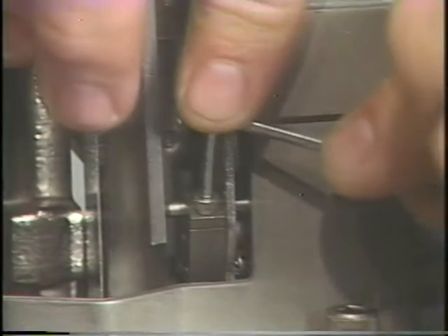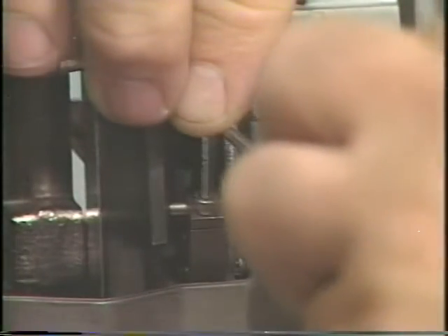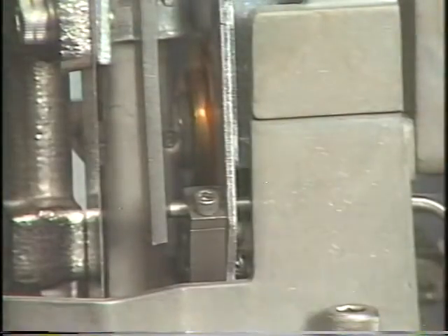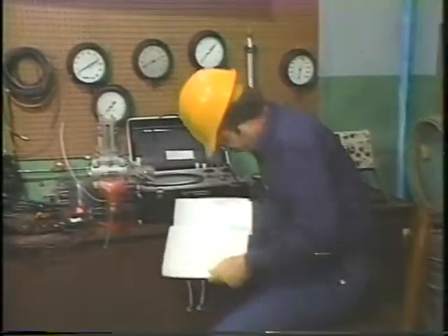Now, when Bob gets back with the new nozzle, he's going to install it in the transmitter. Then he'll have to calibrate the transmitter, making the necessary zero and span adjustments. He'll also have to make the repeatability check. For replacing any major components in an instrument, such as a nozzle in a transmitter, the service manual usually contains the procedure you'll need to calibrate the transmitter correctly. Actually, in fixing the transmitter, Bob will have to first replace the nozzle, then calibrate the transmitter according to the instructions in the service manual.